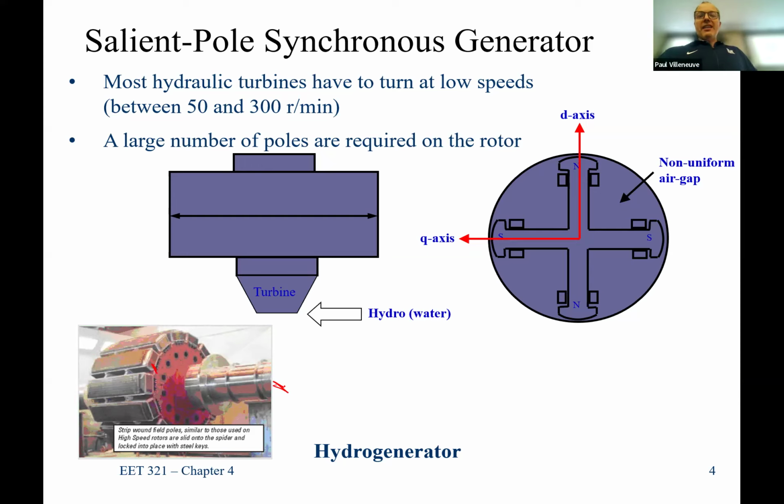You also see that here is our rotor circuit, and this is a how many pole machine? Can you tell by looking at it? 4 or 2? Let's count. 1, 2, 3, 4. So it has 4 poles or 2 pole pairs. So what synchronous speed would this machine want to operate at? 1800 RPM. That's at 60 hertz, not at 50 hertz.